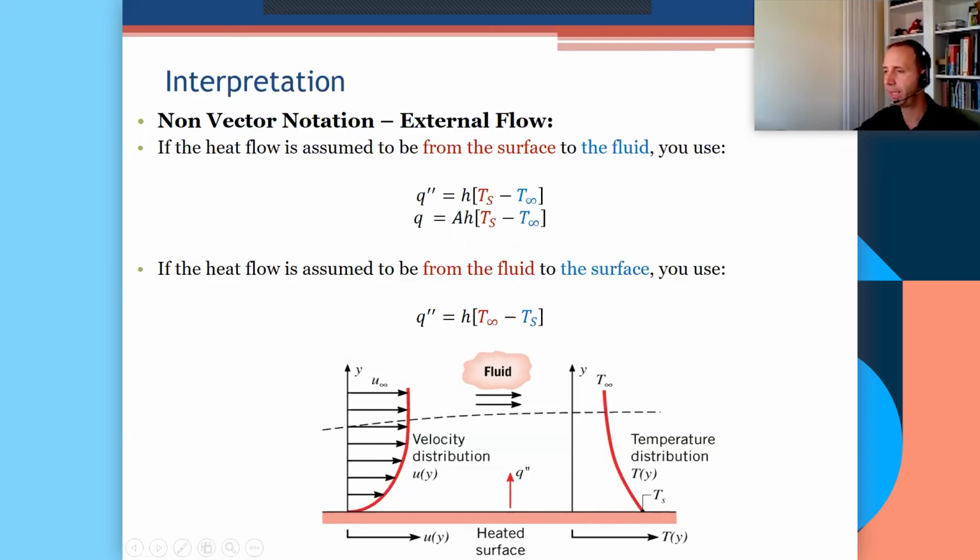So this is just a schematic representation of what happens. If you've got fluid flow above the plate, then you've got a gradient in temperature. We have what is called a no-slip boundary condition, which guarantees that the fluid particles right at the wall will take the same velocity as the wall itself. As you move away, if the fluid goes faster above, then you have a gradual transition. The temperature behaves in a similar manner. That is, if you have a temperature difference across, you'll have a gradual transition from the temperature of the surface to the fluid.